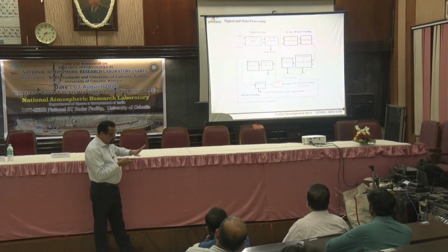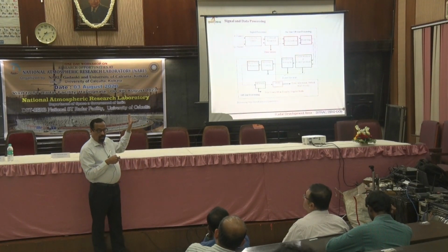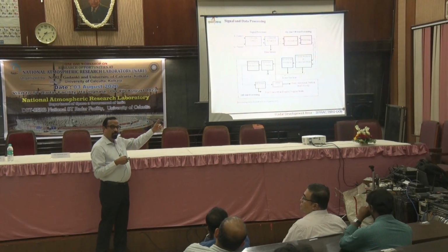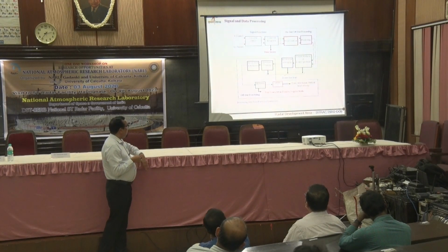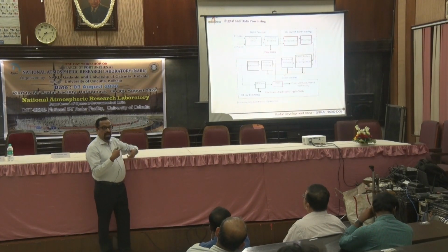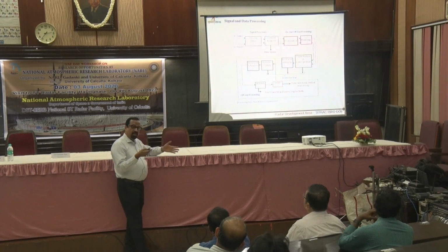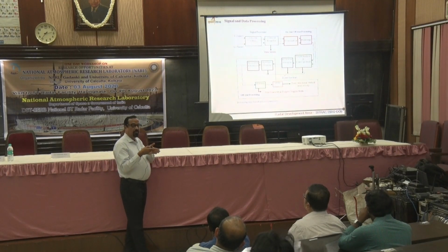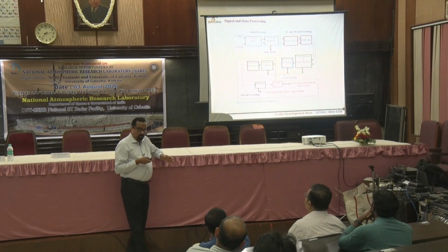I will not take any questions. I will just go through it orally here itself. We do the decoding. Once a pulse is transmitted in coded form, we have to retrieve the information. That is what we call decoding of the signals. Then we do coherent integrations. That is nothing but a gain introduced in this system: an oversampled signal reduces its samples by adding adjacent, repeated signals together to make a single point. What is the effect of that? We are actually filtering the signal also.